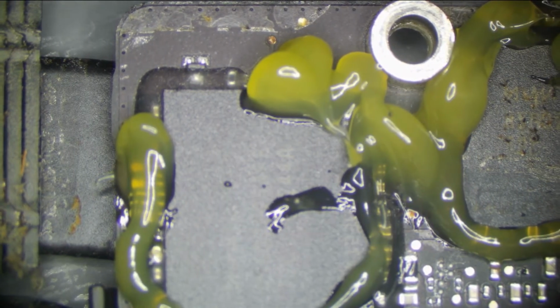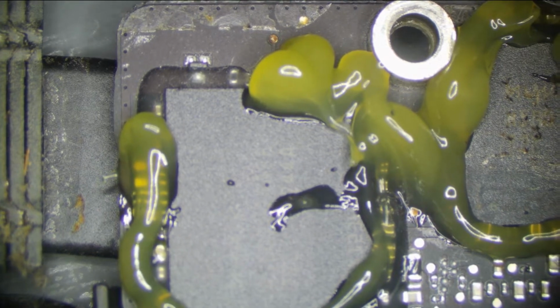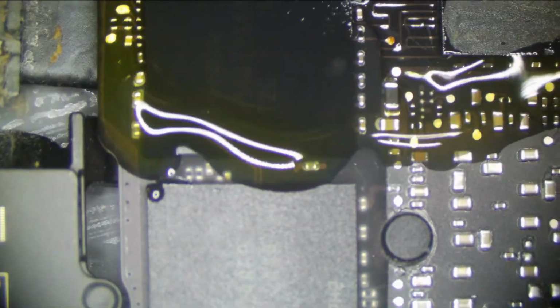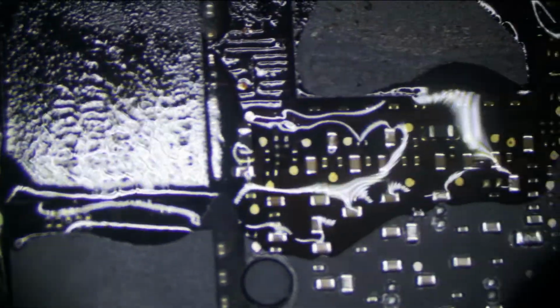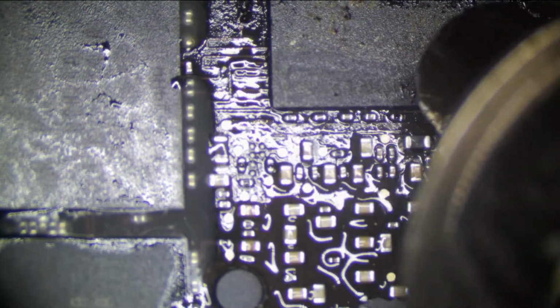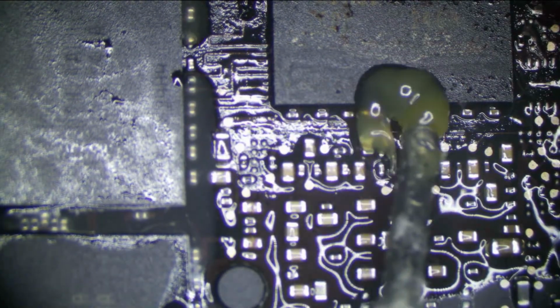and then it's going to go in the ultrasonic, of course. So what we're going to do, we're going to lower our temperature to make sure we don't melt the solder. We're going to lower it to like 300. That's enough to activate the flux, but not enough to reflow the solder joints under it. So I just want a nice amount of flux to go under these. Sometimes we may have to reflow completely, but I don't want to. I just want to get enough under there that it's going to heat up and destroy the corrosion under it.